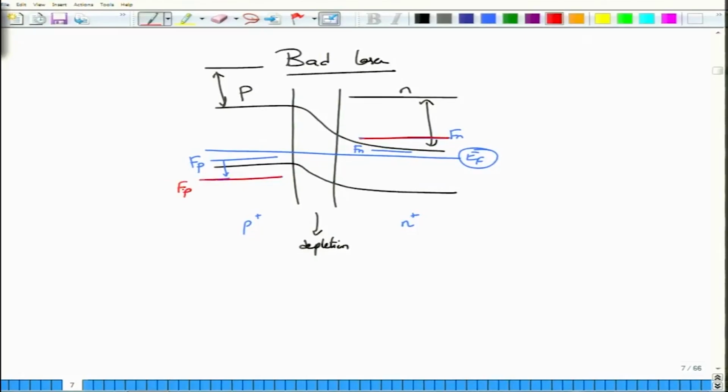To form the lasers, it is not sufficient for us to create just some amount of electrons and some amount of holes in the conduction and the valence band. We have to dope so heavily that the quasi Fermi levels for the holes and electrons actually fall into the band itself. Of course, in that case the Fermi levels are not going to be aligned, as this is the non-equilibrium case. The other condition is that the barrier height also reduces, because you have now started to forward bias the junction. Reducing the barrier height means the electrons which are here can easily, or at least reasonably easily, move to the p side region, and they diffuse while they do that. The holes which are present here will also move into this region, and when they are there, they will recombine to emit light and create a laser.